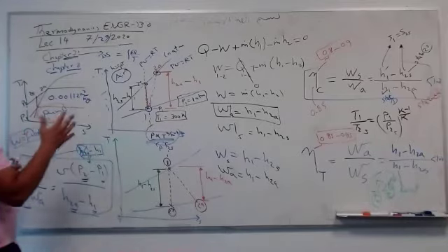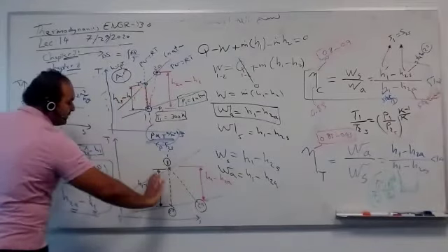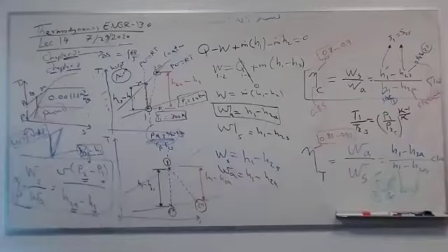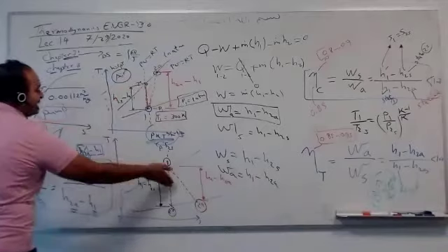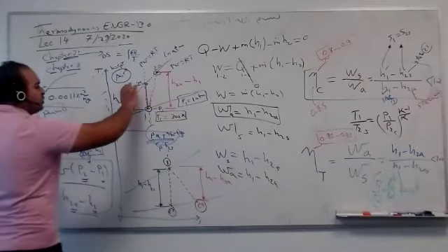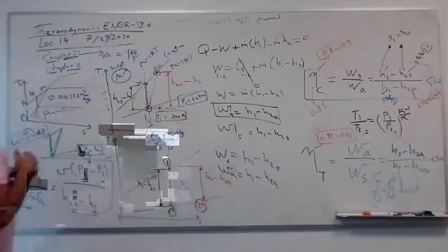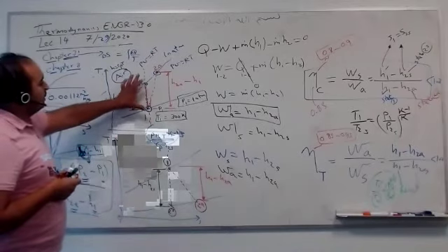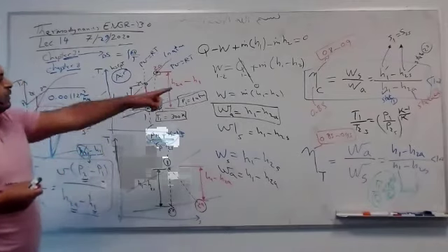So what happened here, guys? Again, this is the minimum to pay for the compressor, and this is the maximum to pay. I wish to be at 2S. The problem is I'm not. I'm at 2A, paying more, getting less. So we take the ratio of the shorter to the longer. Here the shorter is isentropic, or reversible, over actual, and we call it eta compressor.